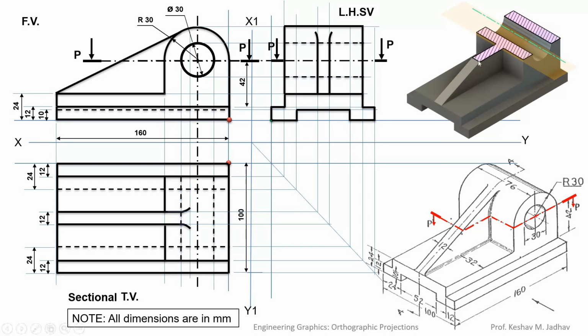So to draw this line, we have to take the projection from this intersection point from front view to the top view. And we have to show the hatching lines for this cut portion. So cut will start from this. So we can draw hatching lines like this. Hatching lines are the lines at 45-degree inclination and spacing between two lines is equal. So these hatching lines are the lines at 45-degree inclination, equally spaced.